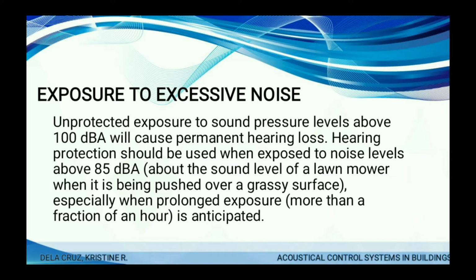Hearing protection should be used when exposed to noise levels above 85 dBA, about the sound of a lawn mower when it is being pushed over a grassy surface, especially when prolonged exposure of more than a fraction of an hour is anticipated.